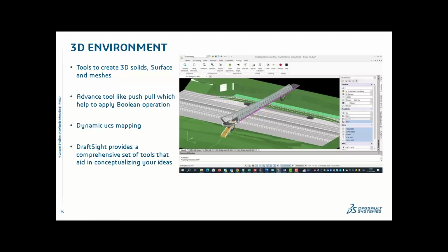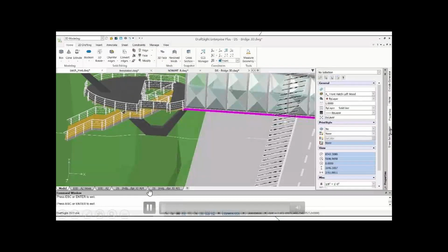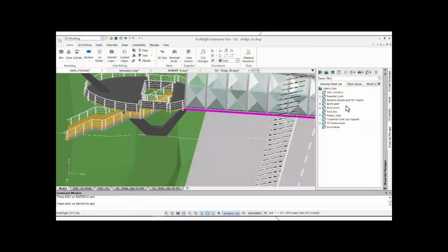So next we move on to the topic Sheet Set Manager. By the way, I consolidated my whole project using the Sheet Set Manager. It lets us create, organize, and manage drawing sheets within the drawing sheet set, creating sheet subsets which are often associated with the disciplines.